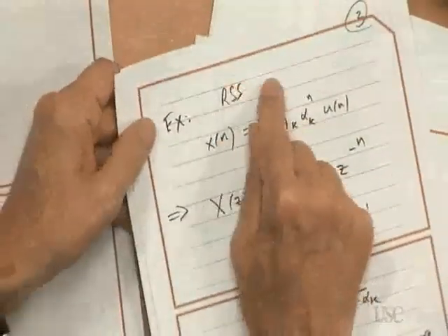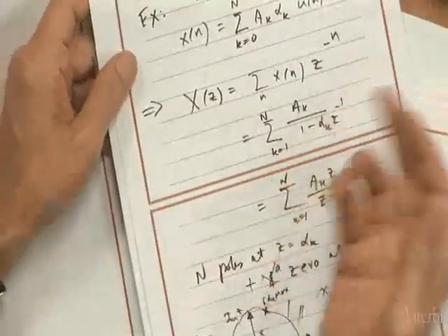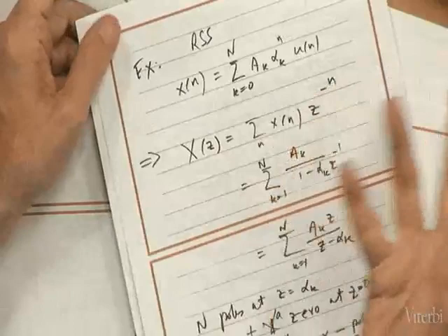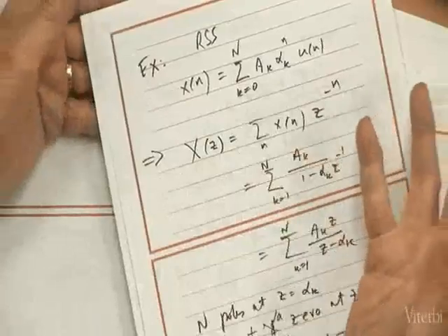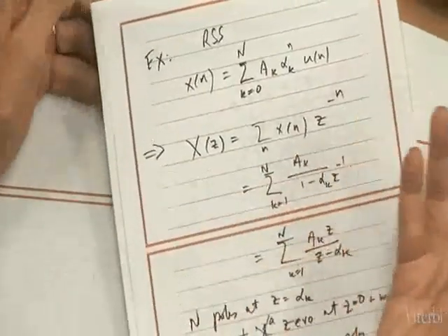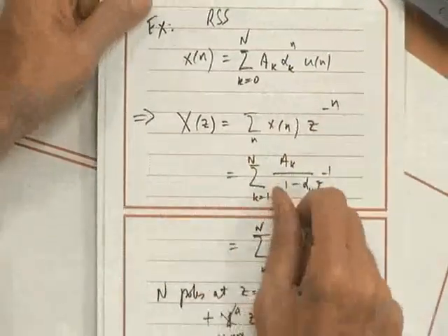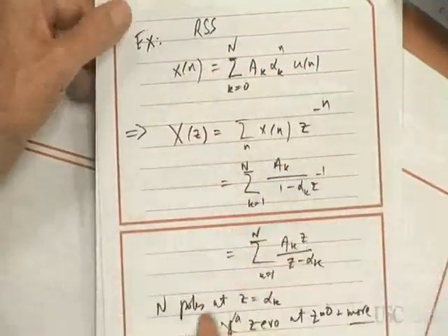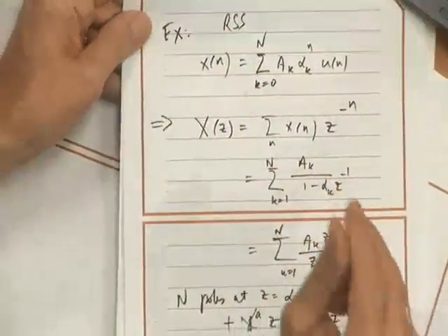We talked about right-sided geometric sequences, and we found that in general, for the Z transform you have to specify a region of convergence. Now, that region of convergence could be the entire complex plane. It could be nothing. A Z transform may not even exist, in which case the region of convergence is the null set or the empty set. Typically, the region of convergence is a continuous region, and it's bounded by some circle, or it could be 2 circles, depending on the sequence.